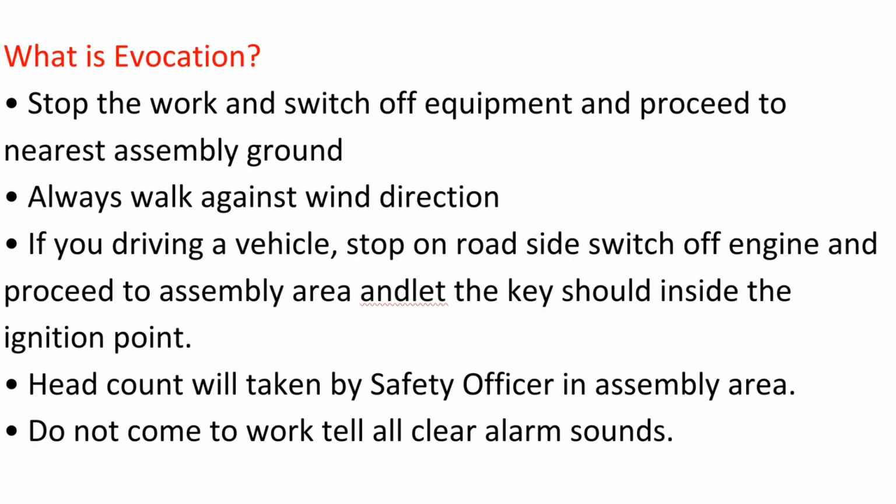Question: What is evacuation? Answer: Stop the work and switch off equipment and proceed to the nearest assembly ground. Always walk against wind direction. If you are driving a vehicle, stop on the roadside, switch off the engine and proceed to the assembly area and leave the key inside the ignition. Head count will be taken by the safety officer in the assembly area. Do not come to work till the all clear alarm sounds.